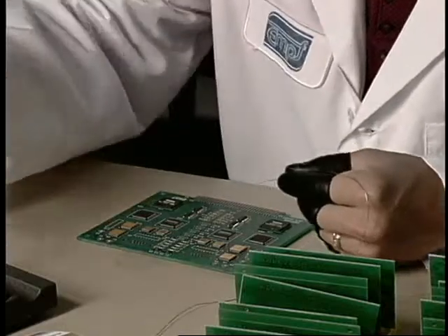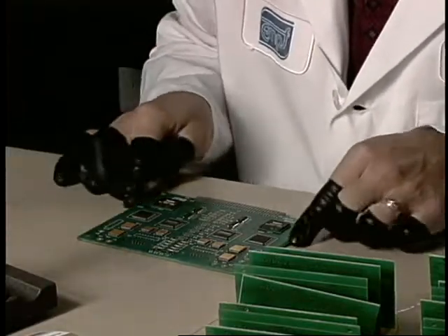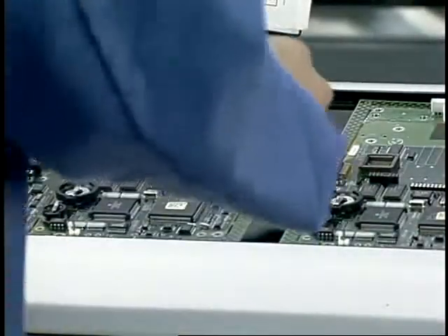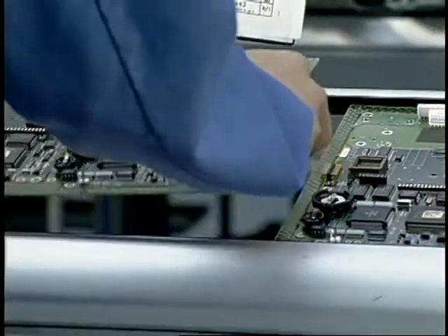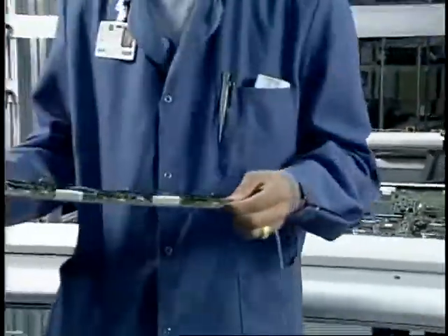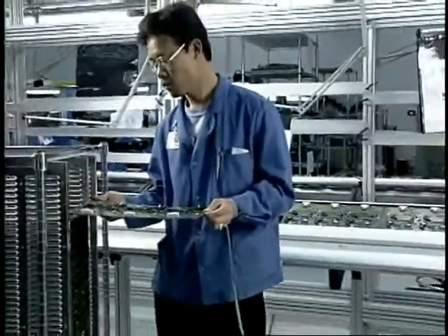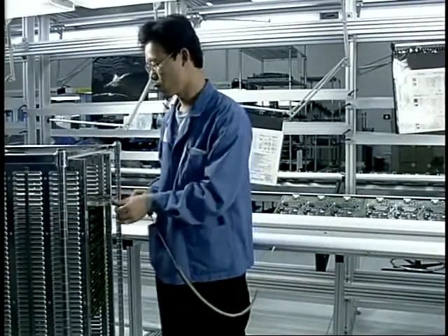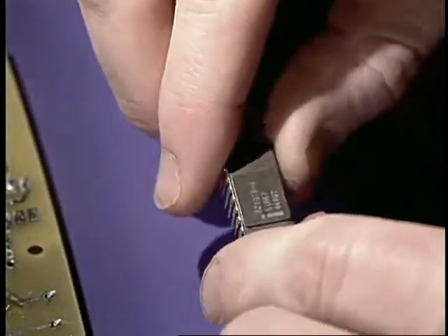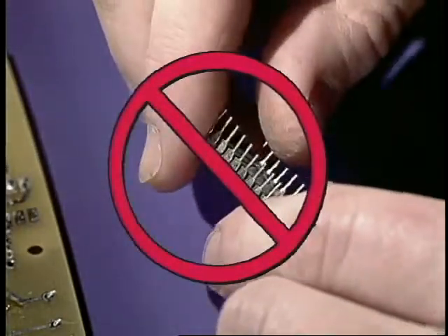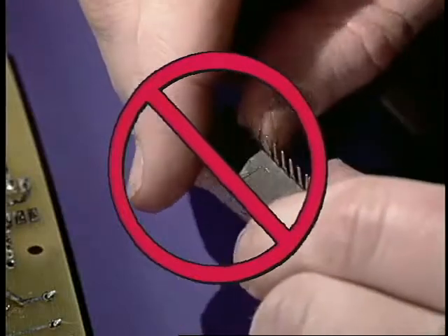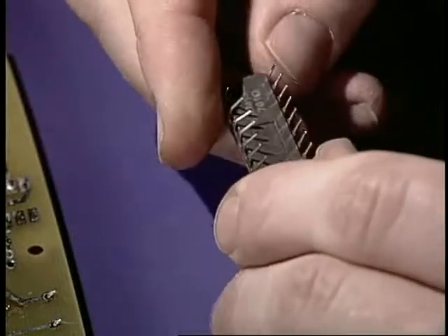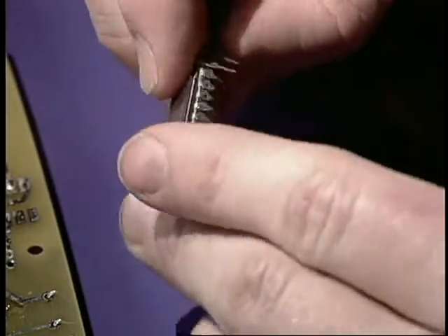Another concern in electronic assembly is the handling of the bare boards, components, and finished assemblies. Boards and finished assemblies should only be handled by the edges. Residues of oils and salts from your hands can cause contamination in the circuit areas and ruin the solderability of a circuit board. In terms of the components, it is important never to touch the device leads or contacts. Oils from your hands can produce poor solderability. Also, the component leads are fragile and can be easily broken or bent.